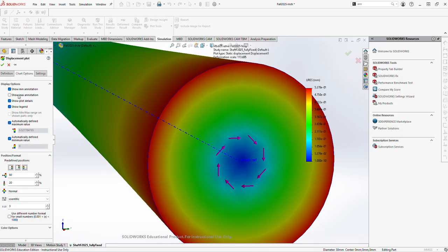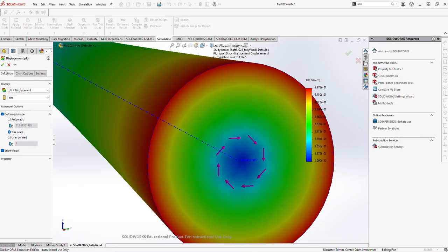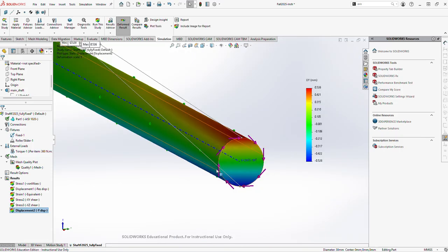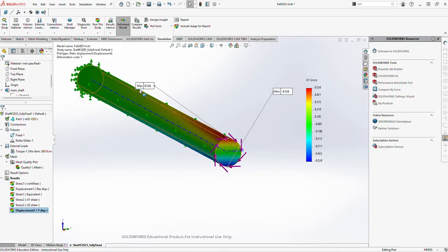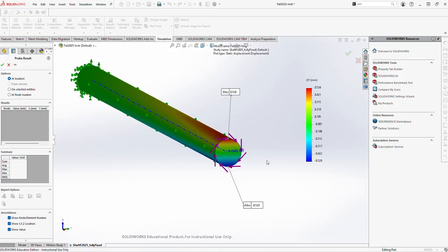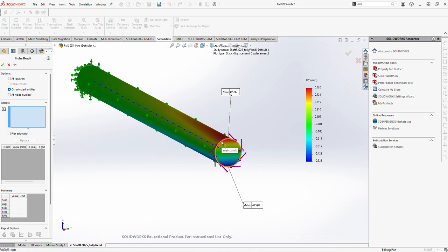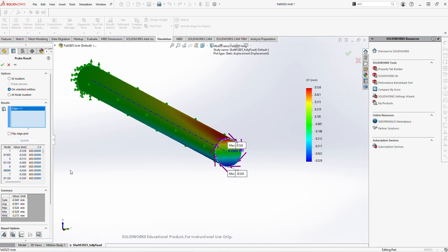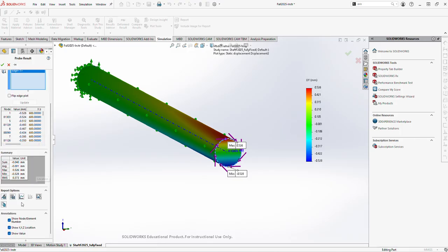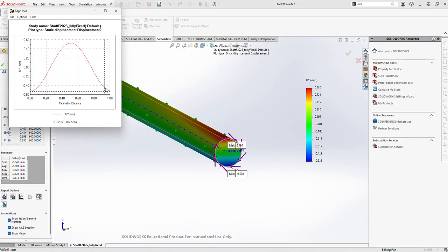I will go in again, show minimum maximum and also floating, and I have chosen millimeter as the units. And now you can see here that these are the maximum and minimum locations for the displacement at the free edge. And again, you can plot this for the entire edge. Before I do that, I'll quickly go on to the probe tools on selected edge. This time I'm choosing the free edge, and I will click on update, and then I can actually show you the variation of the displacement.